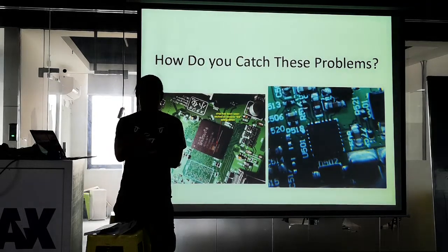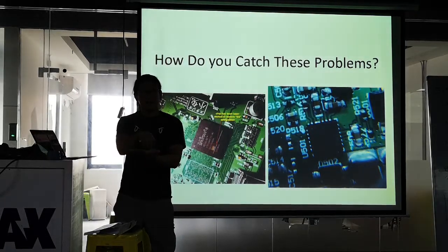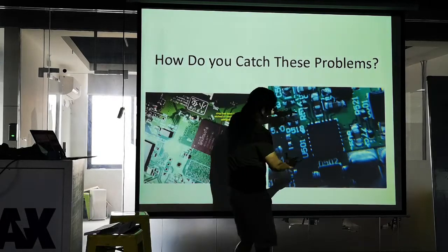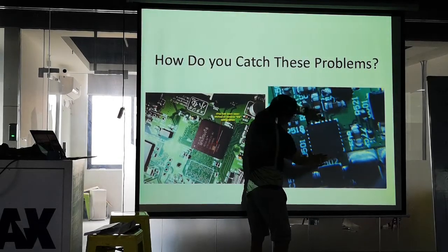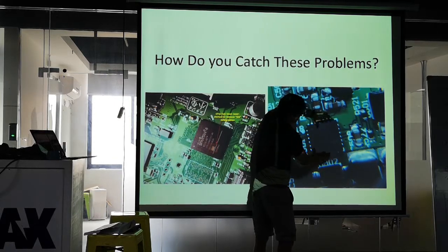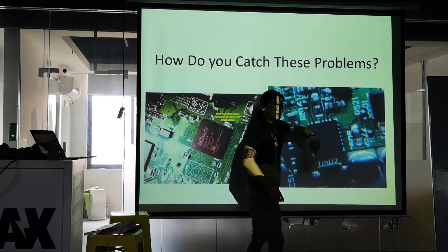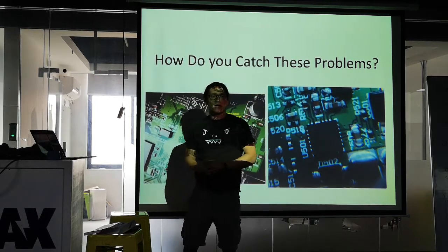And then the gas can make the chip jump off of its pad slightly during that time. And so you get QFNs that are mounted here, but then off by one pitch, right? Or you'll have the QFN that wiggled around and pulled solder across two pins. This is unfortunately a really common problem with the QFNs.